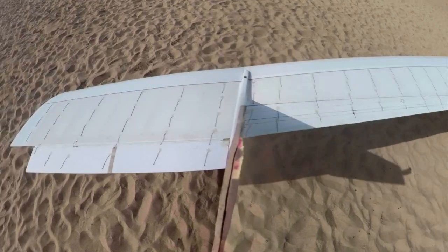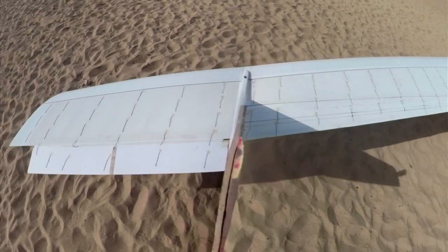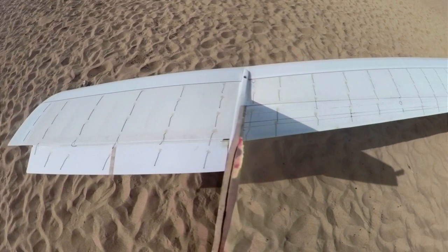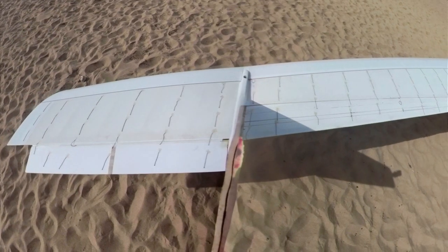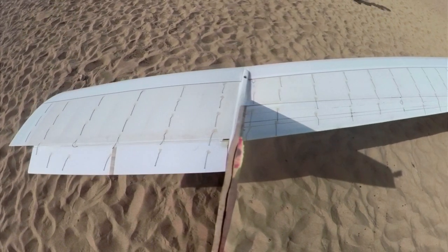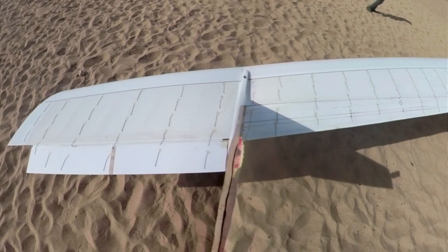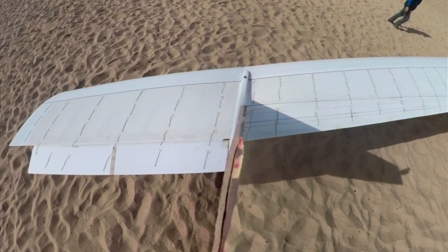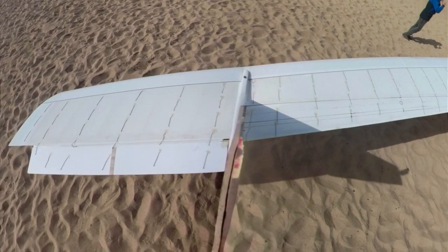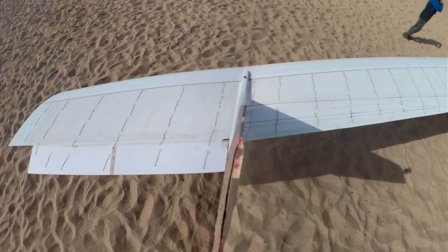And I have double the roll rate. I added this chunk of Elevon. It's not huge, but it is significant. And I have really nice roll rate now. And it's very easy to handle the glider on the ground. And I'm not getting massive amounts of flow separation. So at this point, I figure good to go.